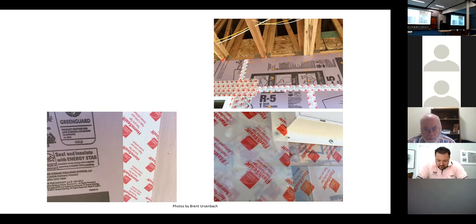If you go to this table for exterior walls in climate zone 5, prescriptive table 402.1.2, wood frame wall, it says R20 or 13 plus 5. So which is better insulation, R20 or 13 plus 5? 13 plus 5 means you have R13 in the cavity and you have R5 on the exterior.